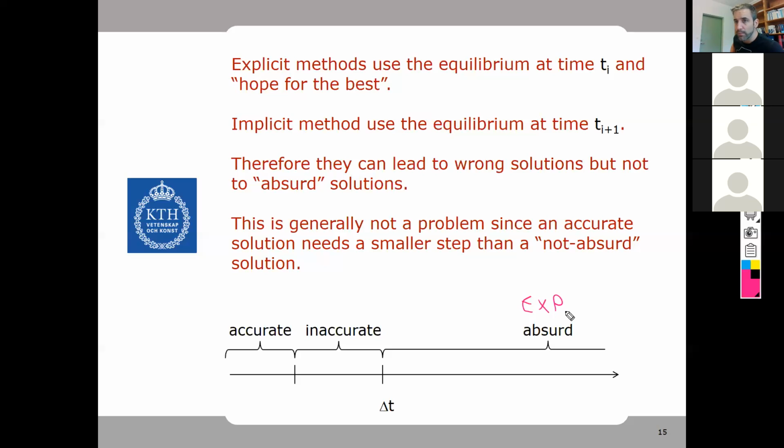And I personally consider that to be a disadvantage, because with an implicit method, even if you use it wrong, your results are going to look good. If you use an explicit method and you use it wrong, it's going to be obvious that it's wrong. And that's good, that's helpful, because we can use that fact to correct our results, to choose a better delta t, all right?